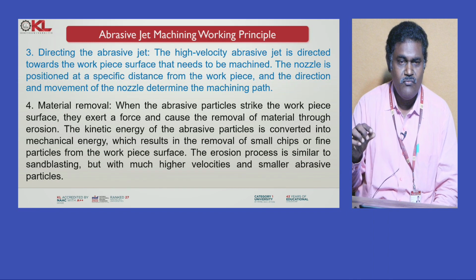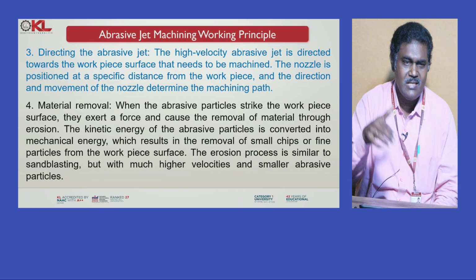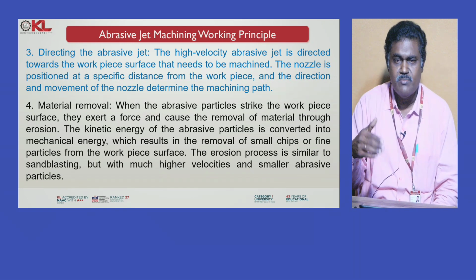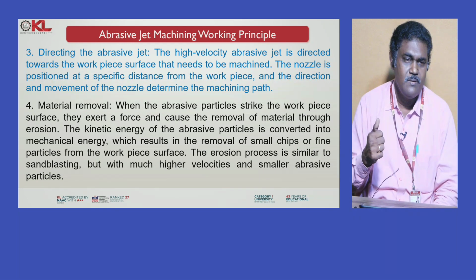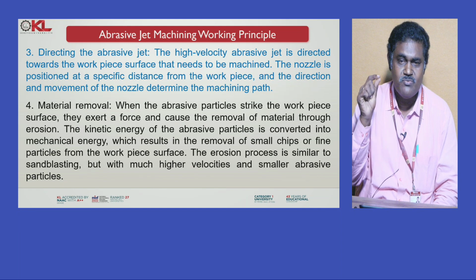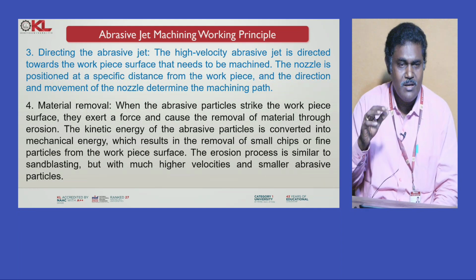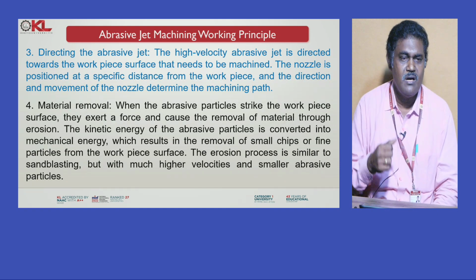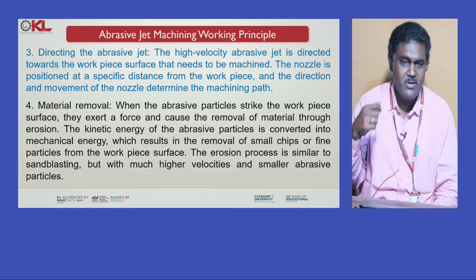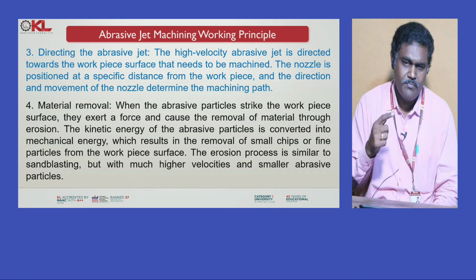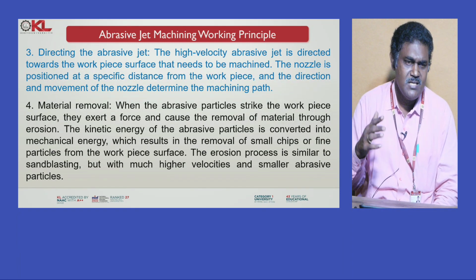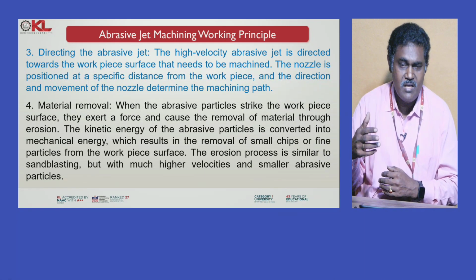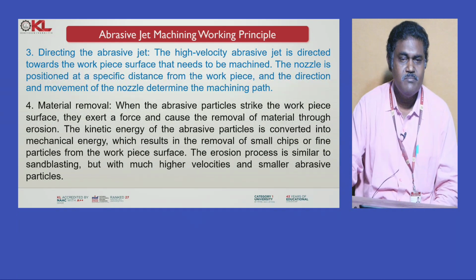Material removal. When the abrasive particles strike the workpiece surface, they exert forces and cause the removal of material through erosion. The kinetic energy of the abrasive particles is converted into mechanical energy, which results in the removal of small chips or fine particles from the workpiece surface. The erosion process is similar to sand blasting, but with much higher velocities and smaller abrasive particles.